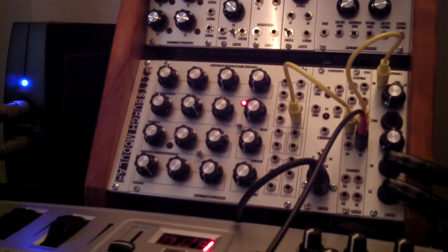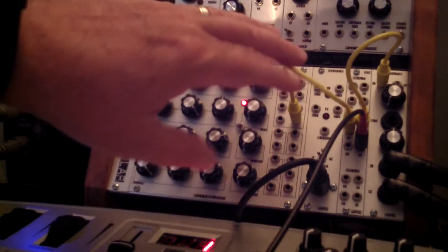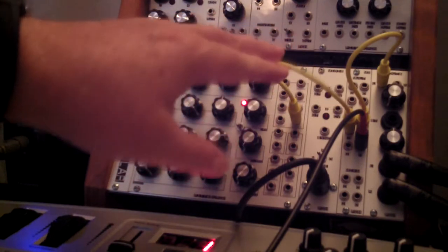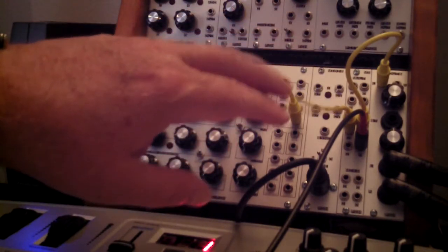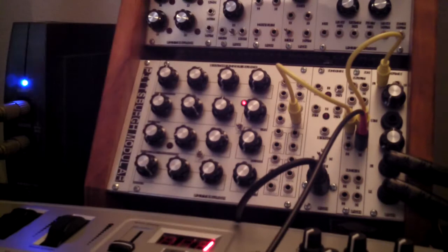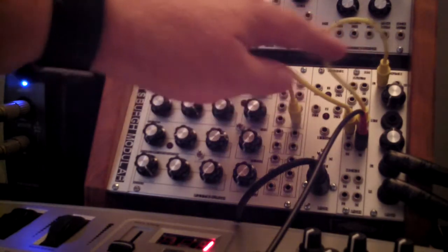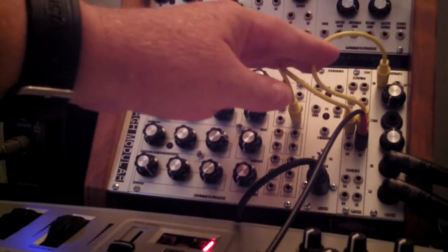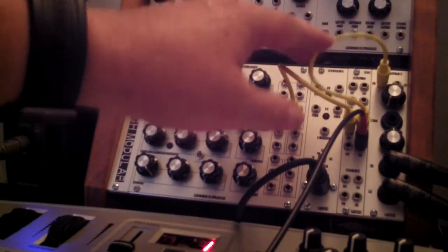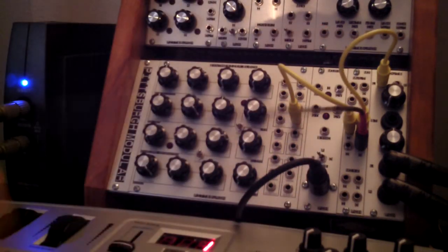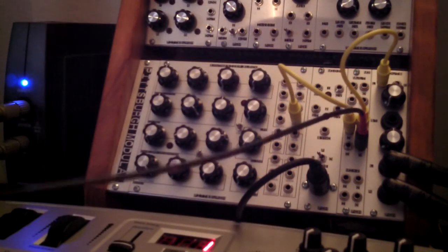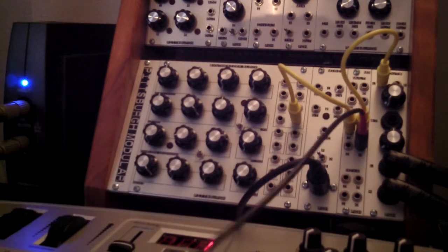I have patched out of the mix output from the synthesizer block directly into the mix 1 section of the M3 module because I wanted to bypass the filter, the envelope generator, and the voltage controlled amplifier. So we'll hear a constant tone as we look at these waveforms, and that is why I then have patched directly out of the mix 1 section back into the outs module, and I've also then taken an output into channel 1 of my USB PC oscilloscope.